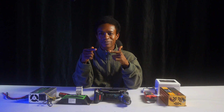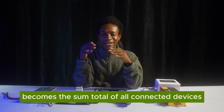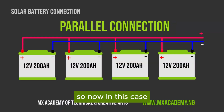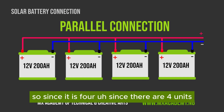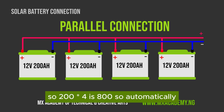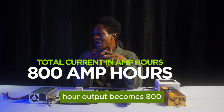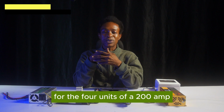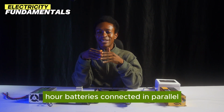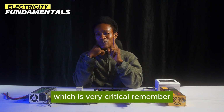So that's rule number 1. Rule number 2, the current becomes the sum total of all connected devices' ratings. In this case the rating is 200 amps for each battery. Since there are 4 units, 200 times 4 is 800. So automatically the total current or the amp hour output becomes 800 for the 4 units of 200 amp hour batteries connected in parallel. That's rule number 2. Now let's look at rule number 3, which is very critical.